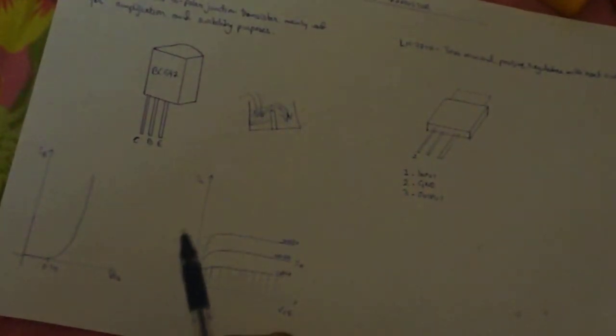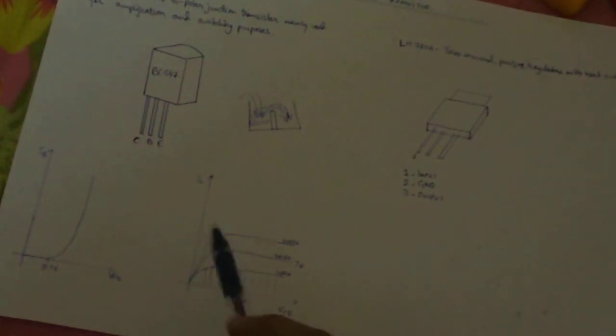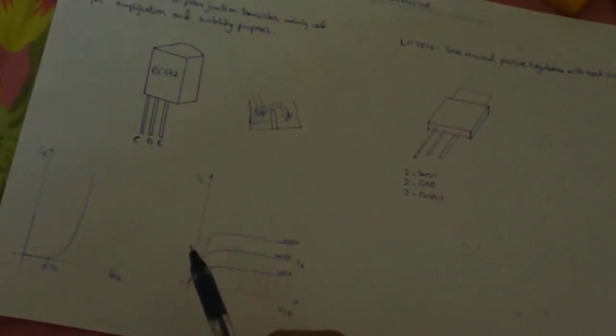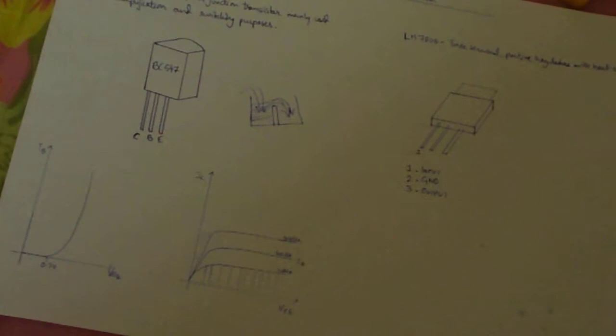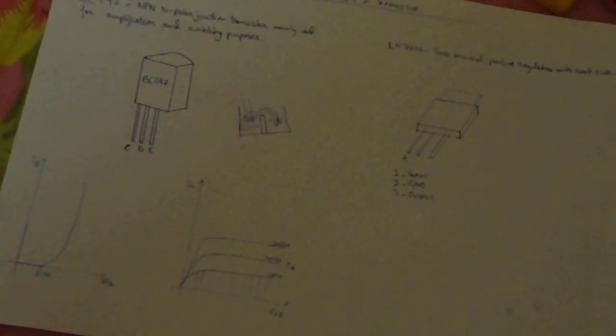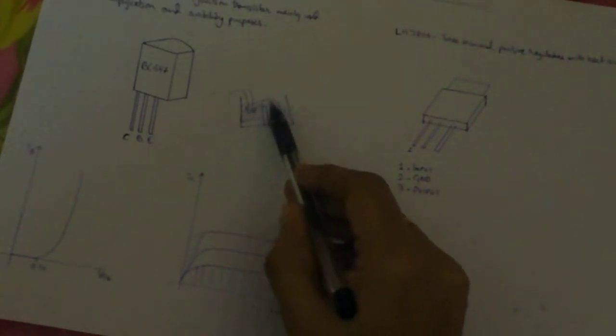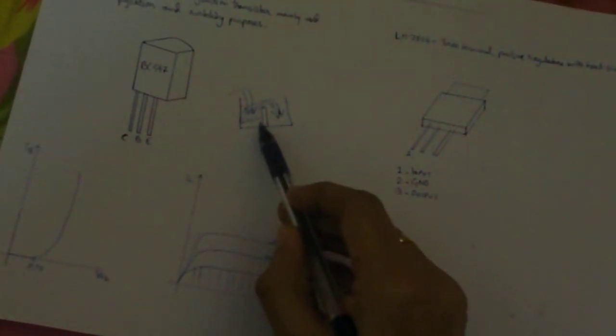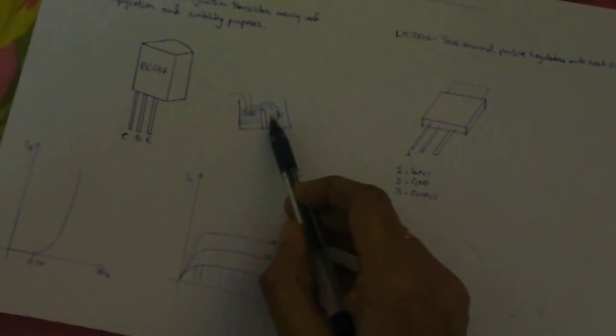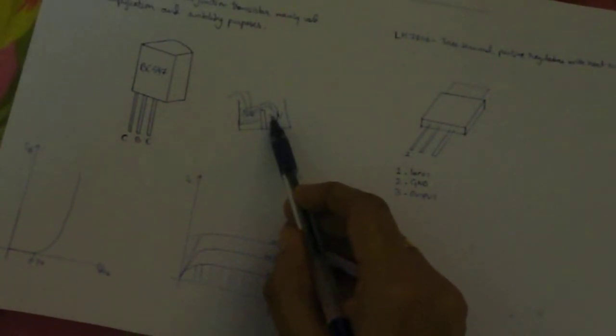When the transistor behaves as a switch, it has an active region and saturation region. When it behaves as an amplifier, it is in active mode. So here we have on or off state. When the current crosses a threshold, it jumps over this wall, and the transistor becomes on.